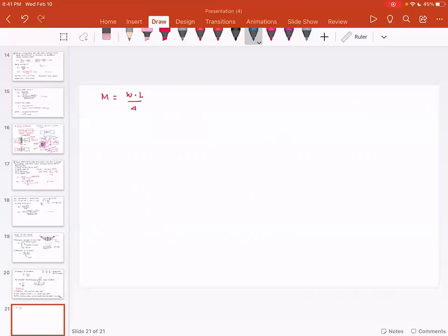And then you can find out sigma B is equal to, that equation is 18M divided by W T square (2NG plus 3NF), where NG is the graduated leaves, so number of graduated leaves. The graduated leaves means the smaller leaves, not full length.